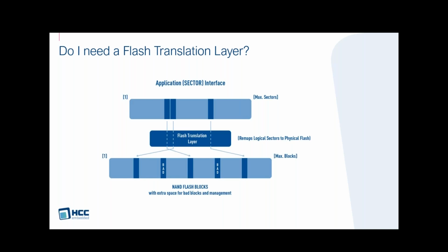The downside to it is that it becomes non-FAT compatible. It's a proprietary solution. So if you're in a closed system, maybe with an MTP or FTP interface, Safe Flash can provide a very good solution for managing flash. But if you want a truly open solution where external devices can access your NOR or NAND flash, then you're probably going to need to use a flash translation layer to manage your NOR and your NAND flash.